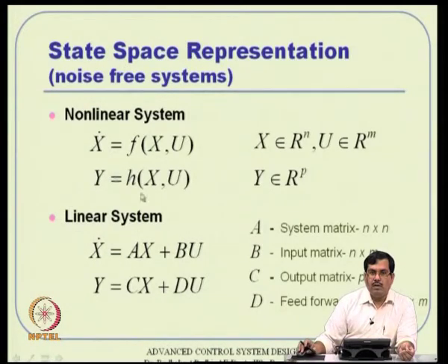So, in general state space representation, mostly we will talk about noise free systems, because the noise input is typically ignored as far as control design is concerned, but it is considered in filtering design, which we will not talk about here, like the Kalman filter for example. These two rely on the philosophy of separation, that you need not talk about noise input directly.